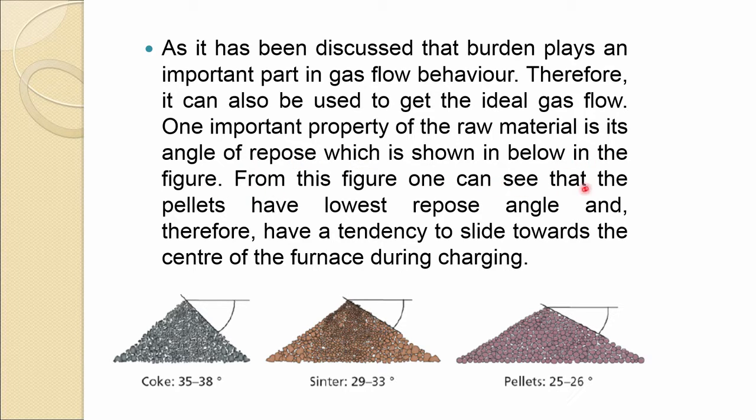From this figure, one can see that the pellets have the lowest angle of repose and therefore have a tendency to slide towards the center of the furnace during charging. As you can see, the coke has a very high angle of repose. The angle of repose is measured from the top surface of the charge with the horizontal line. This angle for coke is quite high, though for pellets it is much flatter.